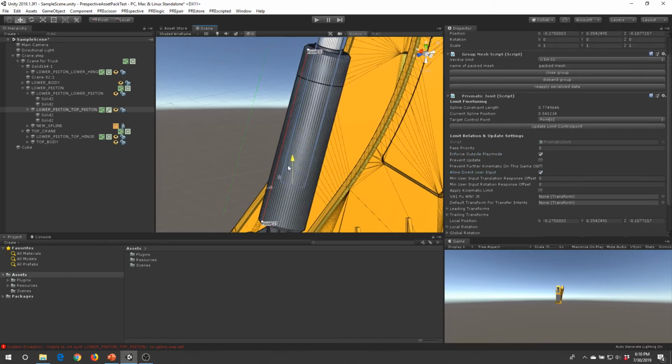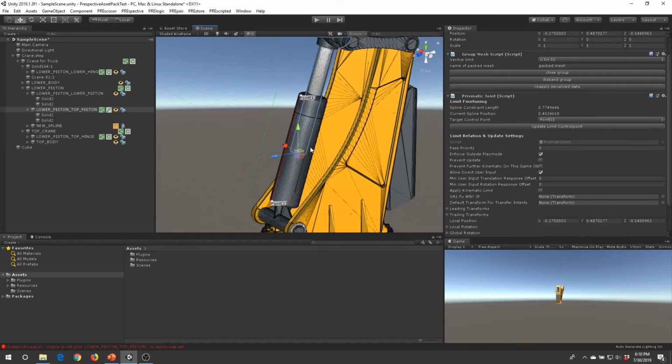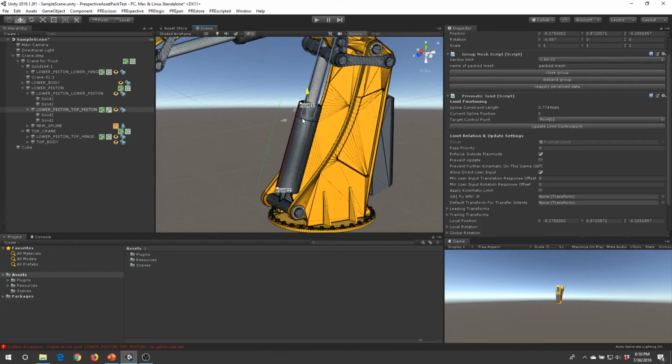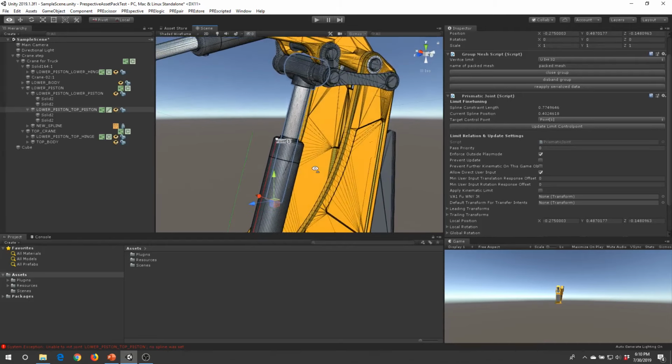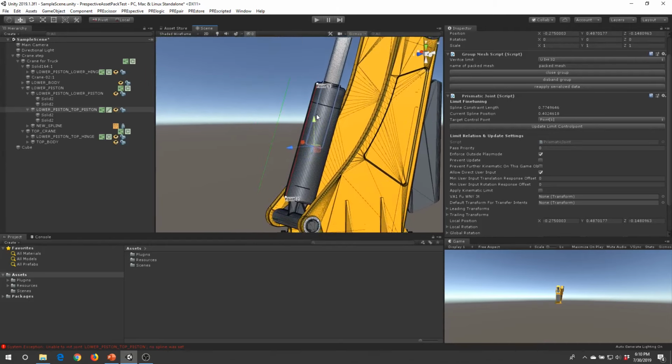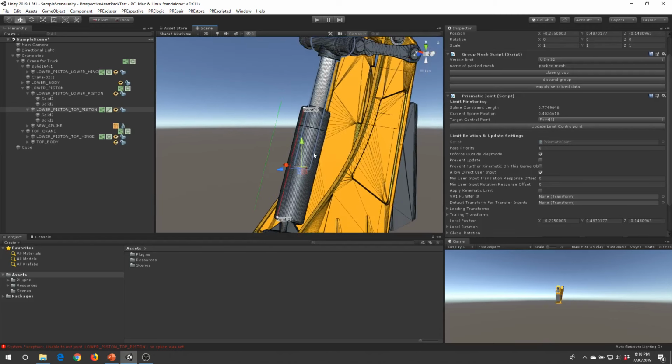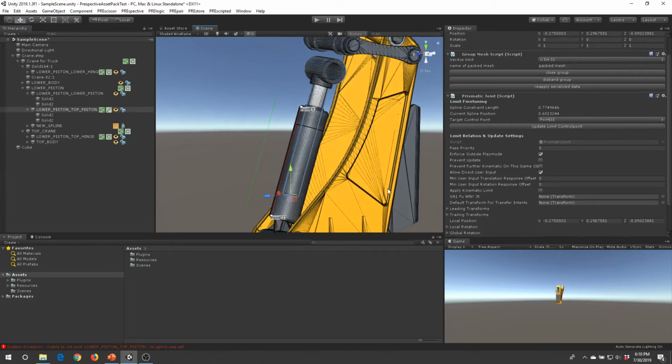And let's see if now it works. So now it actually only allows movement within the range of the spline. I'm just going to use Ctrl Z to get it back to its original position, but the first thing we want to do is have its limits somewhat fixed a bit further. So I happen to know that if I move it back somewhere over here, that's going to be pretty much the maximum offset we're going to allow. So let's just set the limit for 0.2.